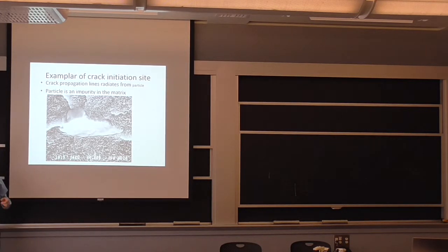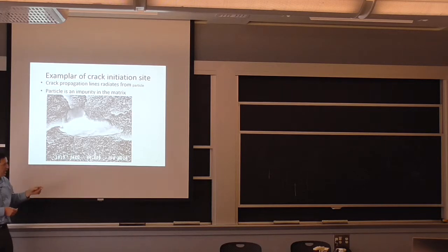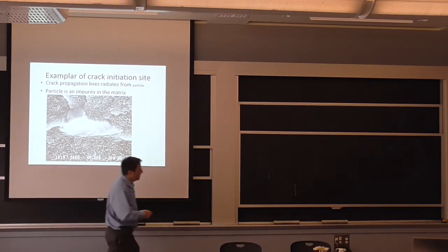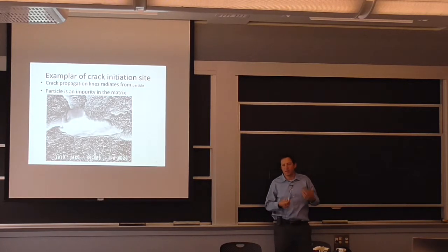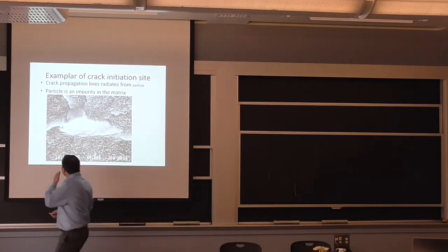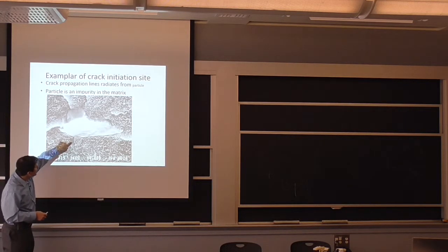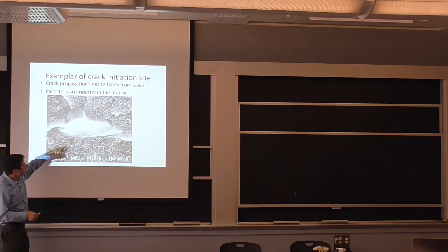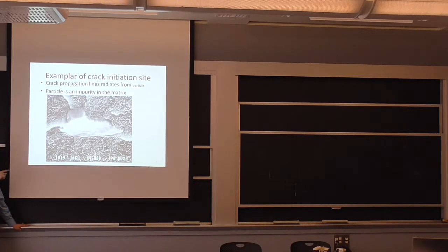This was the biggest inclusion. Now, based on the chemistry of it, it was from the raw material. So essentially, as they process and try to clean these little clay particles, they had one that stayed unprocessed and caused the crack initiation. There's some other particles that are very small, so these actually are the nanoclays, but there's an impurity, and even though it's not on the surface, this was in the middle of the section, that's where the crack started.